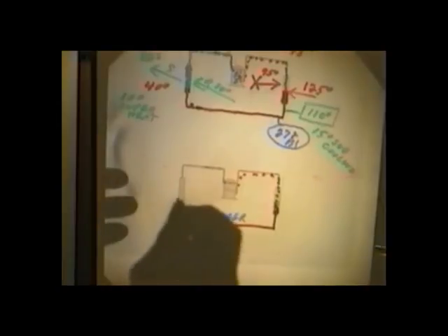But I still have liquid. And now I only have a little bit of liquid in the evaporator. And lots of superheat now. Okay? I've got more vapor to pick up BTUs.